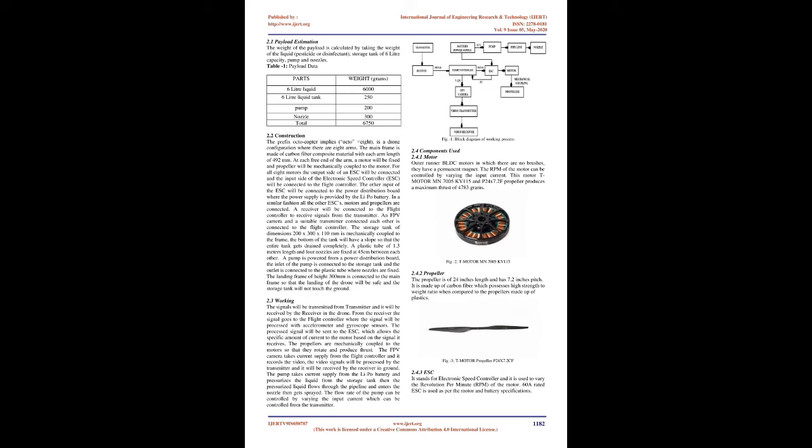Professor B. Balaji et al., 2018, [6] developed a hexacopter UAV with the purpose of spraying pesticides as well as crop and environment monitoring using a Raspberry Pi that runs on Python language. Their UAV also contains multiple sensors like DHT11, LDR, and water level monitoring sensors. From this experiment, they finally concluded that with proper implementation of UAVs in the agricultural field, almost 20%-90% savings in terms of water, chemical treatments, and labor can be expected.